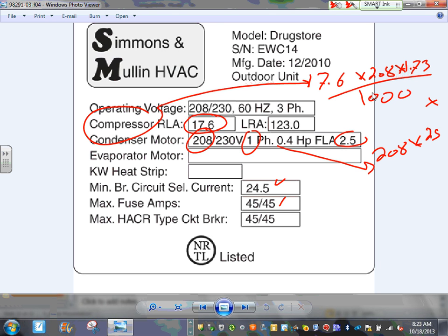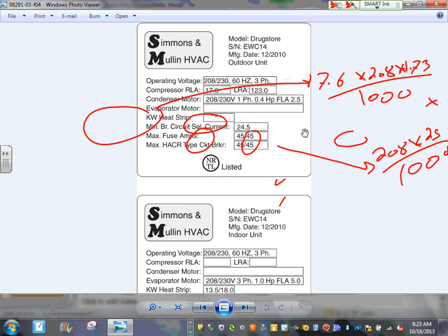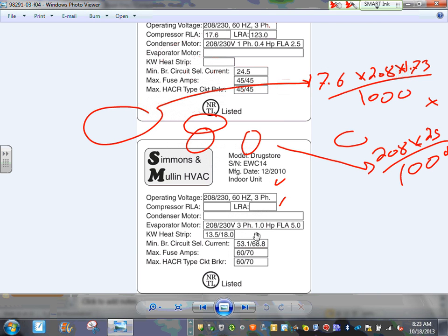In our example, guys, we give you a condenser, and I give you the full load amp of that condenser, so you don't have to do them separately. But if they were separate, that's how you calculate them. You can divide that by 1,000. Yeah, thank you, 1,000. So you can get the kVA, but you don't multiply by 1.73 because it's a single phase. Good point.